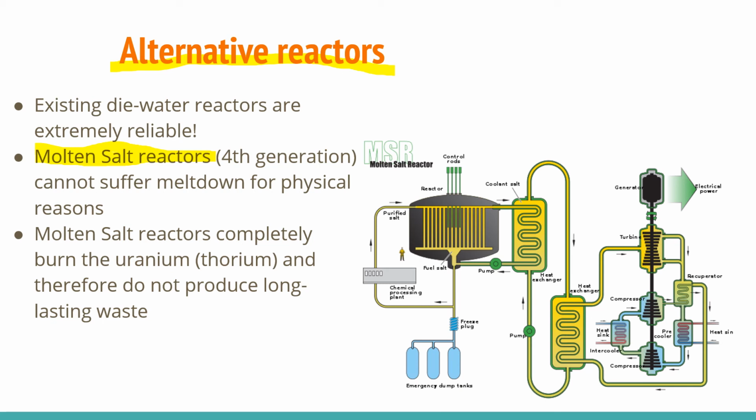But now, if you use this molten salt, you have the molten salt inside of these pipes, and if something goes wrong with this molten salt, then a so-called freeze plug will open. What is a freeze plug? This is a plug maybe made of some metal like, let's say, zinc or tin, with a low freezing point or a low melting point.